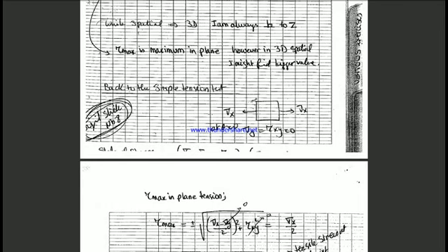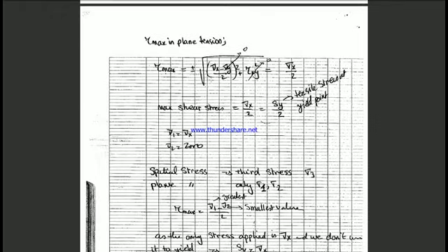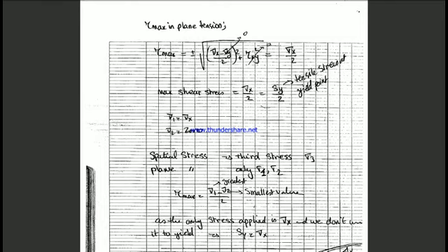So let's go back to the simple tension test. If we have tension, we have sigma x only. We don't have sigma y in this case because it's a simple tension test, and tau xy is equal to 0. So with sigma y equal to 0 and tau xy equal to 0, those equations give tau maximum equal to sigma x over 2.